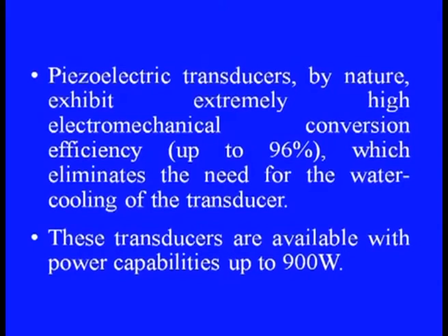The power supply depends on the size of the transducer. Piezoelectric transducers by nature exhibit extremely high electromechanical conversion efficiency, up to 96%, which eliminates the need for water cooling of the transducer. Otherwise, this heat generation in the transducer is also a major problem. Unless we remove the heat through some mechanism, the transducer may malfunction because of overheating. Therefore, in many cases separate or additional cooling is suggested, or interrupting operation of the transducer is suggested. These transducers are available with power capabilities up to 900 watt.